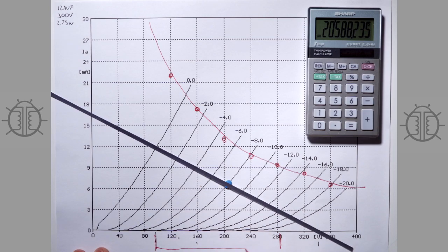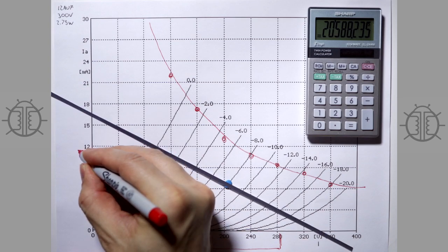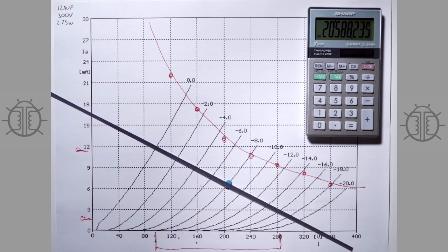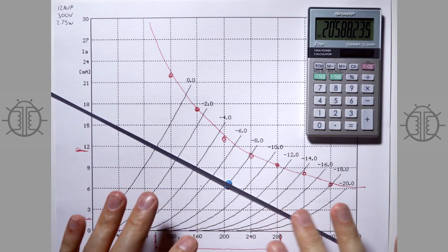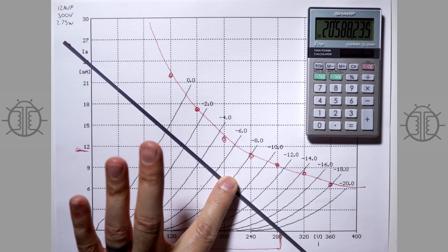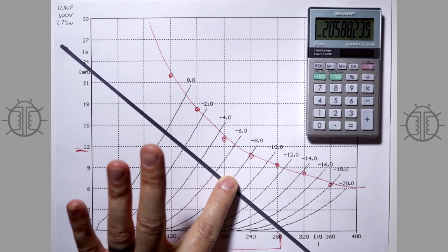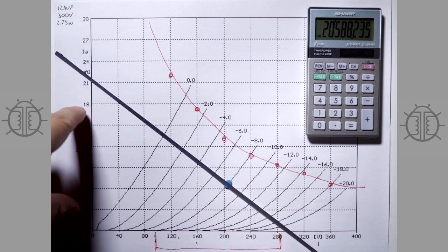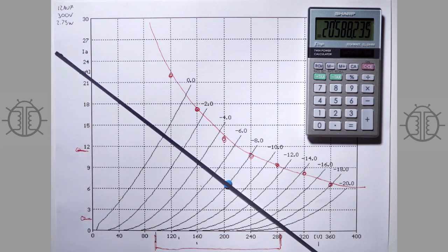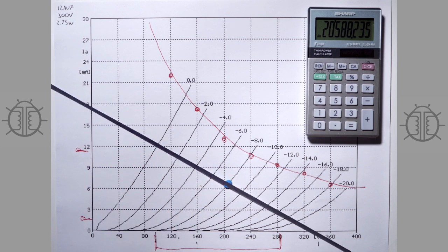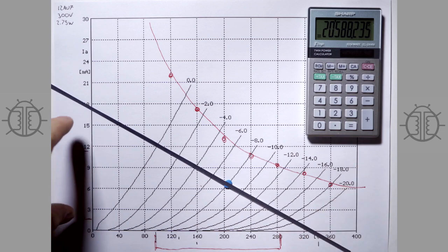So here's your voltage swing. You'll also see that you're swinging current over here, and so you're swinging between right here and somewhere down in here. And so you can see now that if you were to decrease the load, you would change the angle. And what you would do is decrease the voltage that you can swing, but increase the current that you can swing. And so it makes a lot of sense now why, when you load down your circuit, it decreases the output. It's because it requires more current.